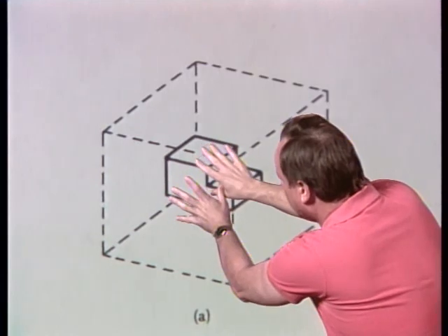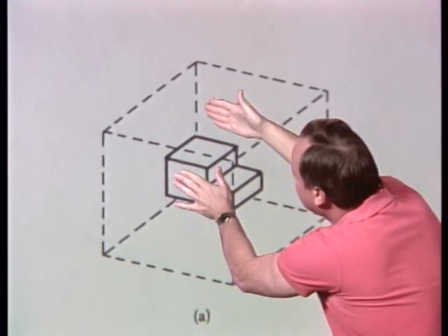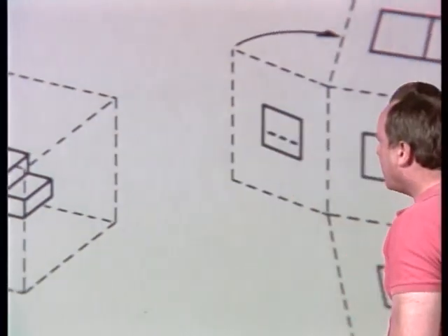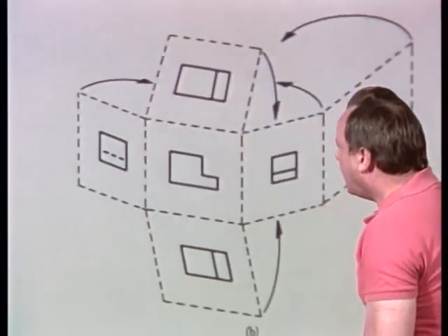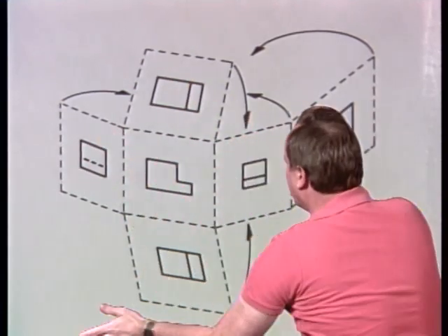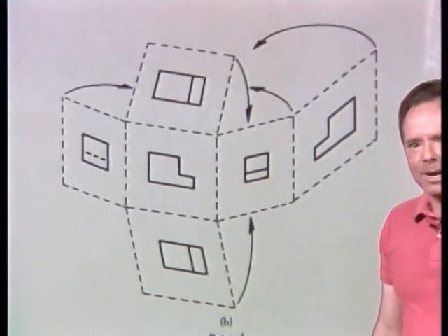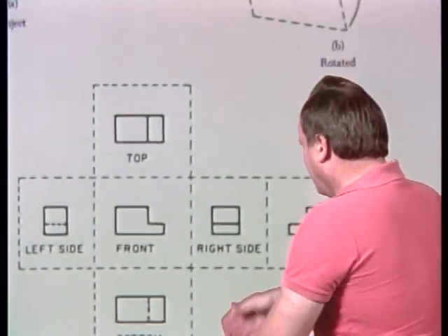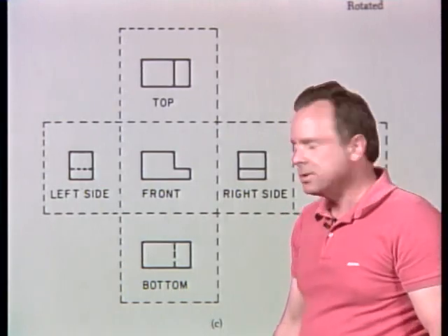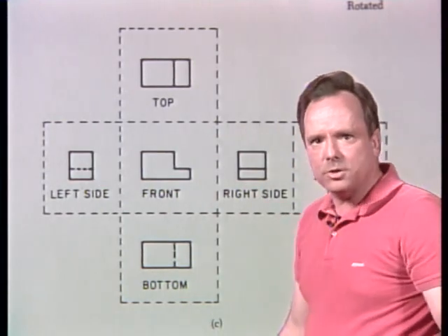The object in the middle of all of these lines, and let's start unfolding a box. Let's go to the upper right corner of this drawing and see that box beginning to unfold. And now you see all of these views kind of unfolding and coming around. And now if you go back down to the bottom, you can see how we got those views. And here are the different views, the 6 views on an orthographic projection. So that's how we got there, just looking just like that.